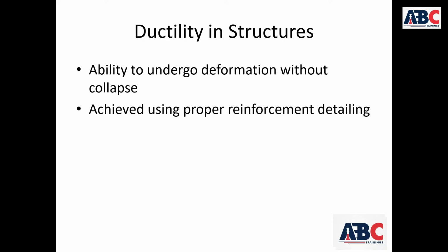How is ductility achieved in RCC structures? Ductility in reinforced concrete structures is mainly achieved by proper reinforcement detailing. Concrete alone is brittle.